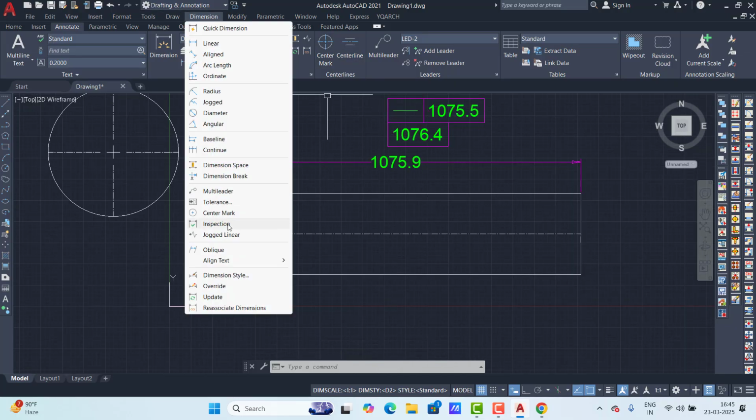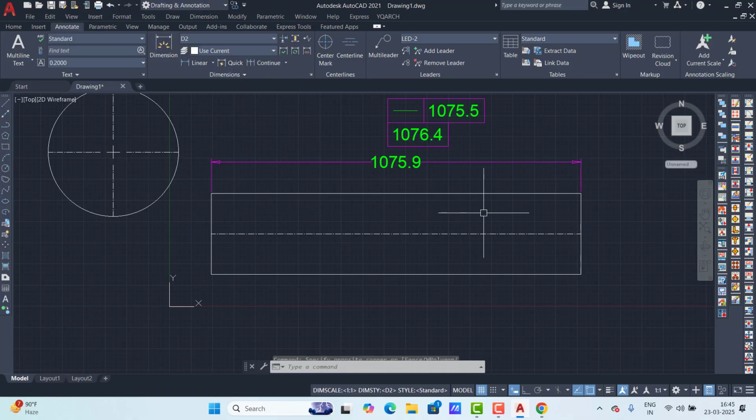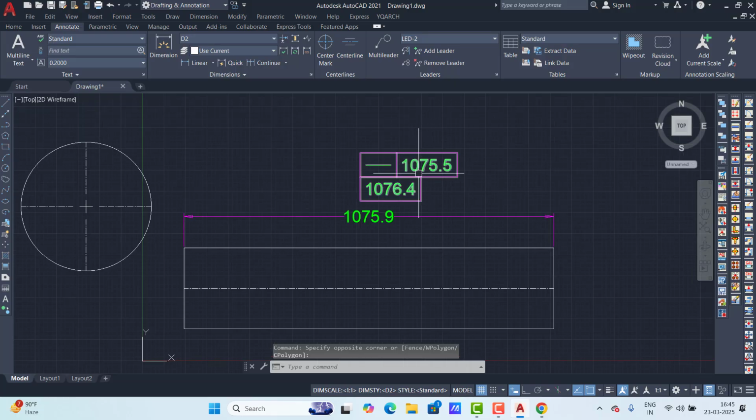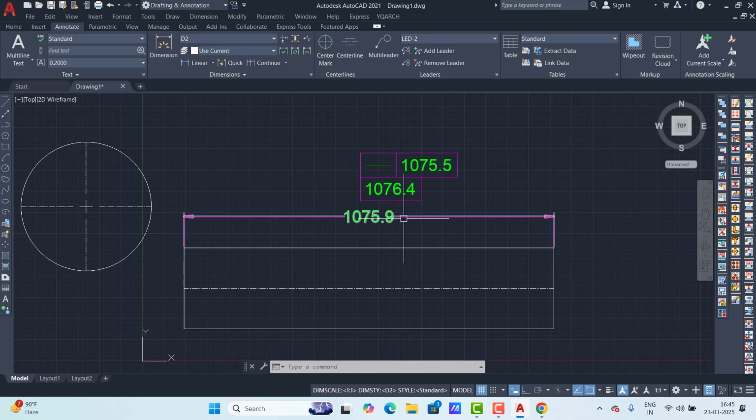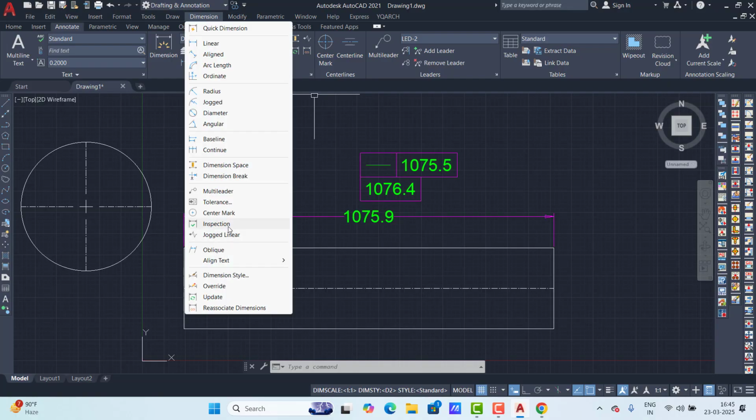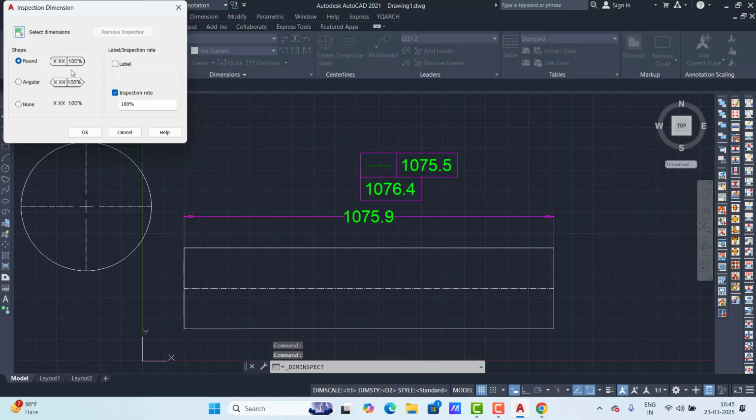Now here I have the oblique option. This oblique option is used only in isometric, not here. Oblique means if you want to rotate a dimension to any angular position, we can use the oblique option, just select it, press Enter and type the angle, so 45. In 2D drawings we do not need this type of presentation. This is only used in isometric. So we make some isometric sketches and then show how to do it. So DS, Enter, isometric snap.